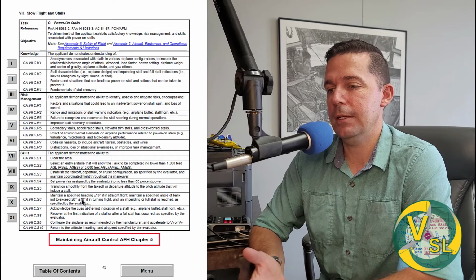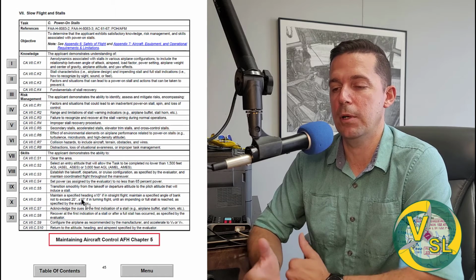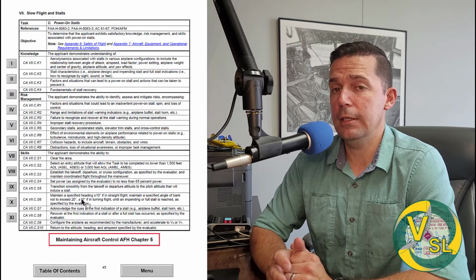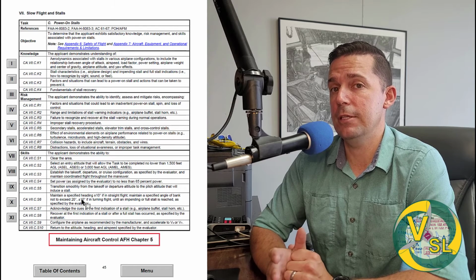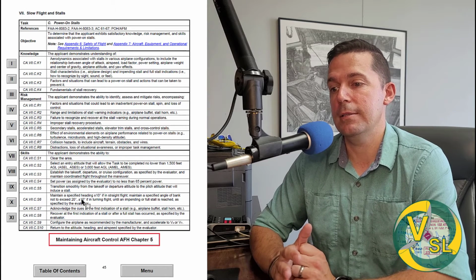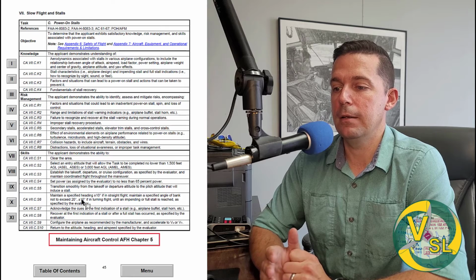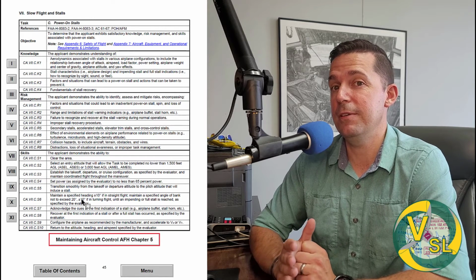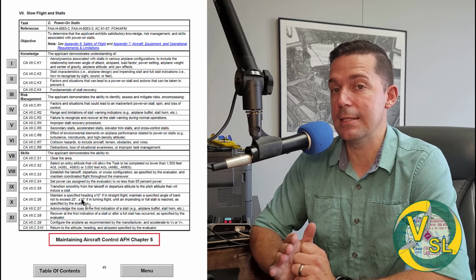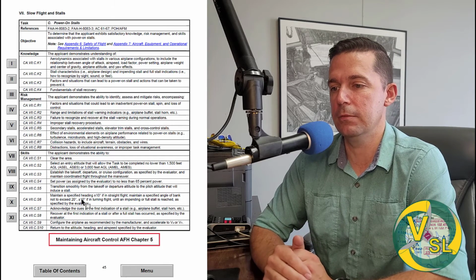And if you're flying an airplane, like we've got a 172 that has an upgraded 180 horsepower engine with a constant speed prop, if you do power on stalls at full power, it will really be pretty aggressively nose high and get a little uncomfortable. So that's where we might back the power off to about 70%, 65% power. The higher the performance airplane, it might be as little as 50% power to get a nose attitude that's safe, especially in a twin. So just some items of note there.